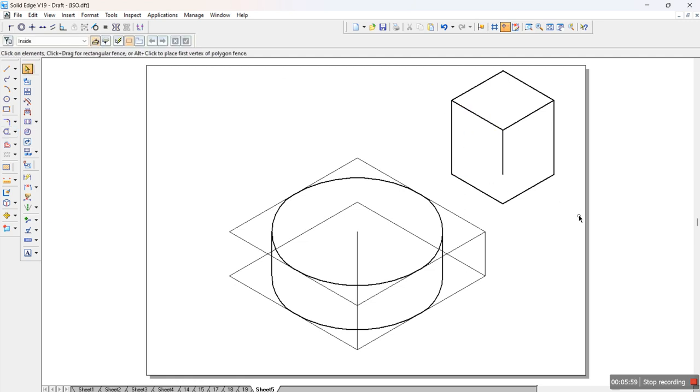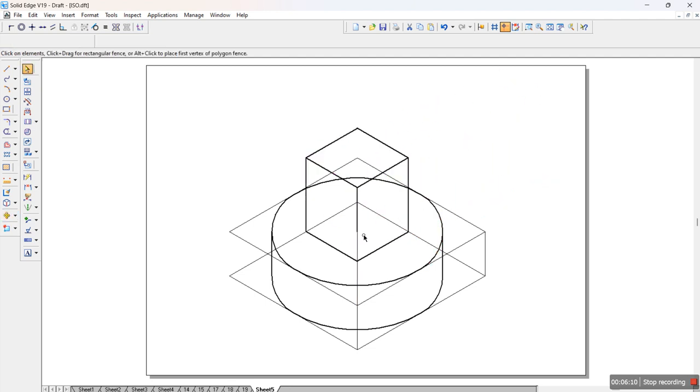Now select this entire prism and place it on top of this particular line, from the end of this to the end of this particular line. Now delete this particular line, these particular lines, and use the extend command under trim, so that we'll have the lines visible. Now again use the trim command and trim the lines that are not necessary. So here this actually completes the problem. If you want, you can trim these construction lines so that it is easier for us to understand